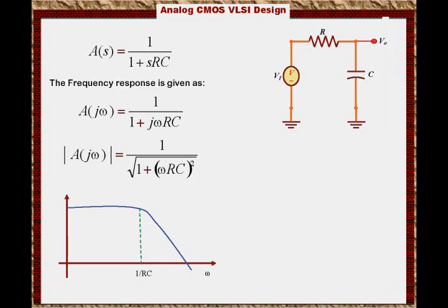It's a function of R and C. Remember that. So basically what this circuit says is that the voltage at the capacitor, or the voltage at the output of this circuit, is flat until I hit the corner frequency, then will start to rapidly drop. The signal will die at the output if it has a high frequency content. That's all what we're saying here.